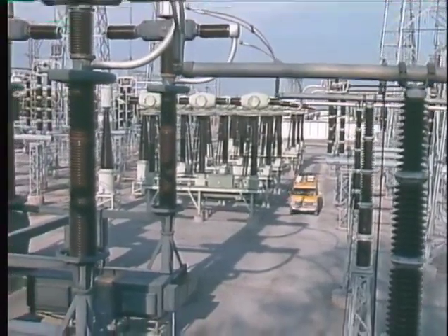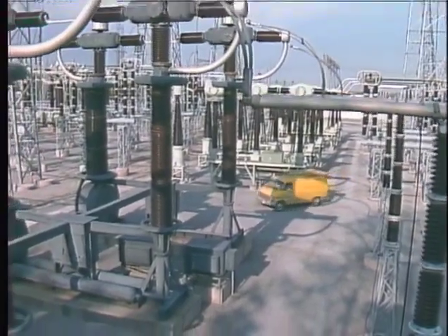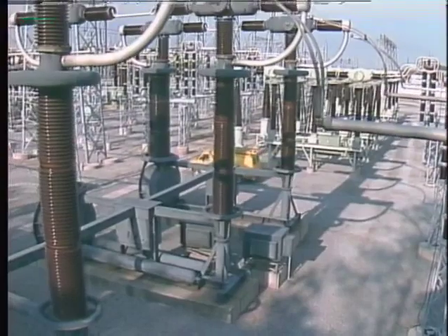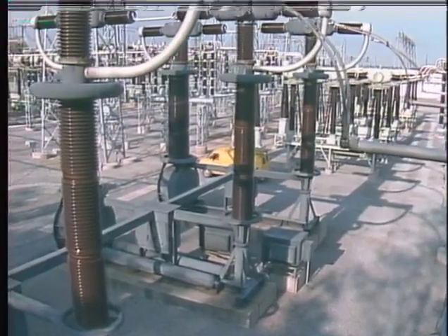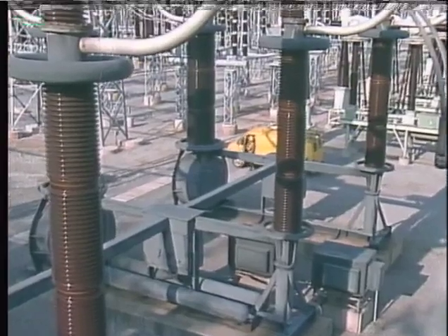Now the last breaker we're going to look at is the air blast breaker. Some checks that are unique to air blast breakers include measuring the space between the arcing rings and stationary contacts, checking the space between the arcing rings and arcing probes, and checking air consumption.